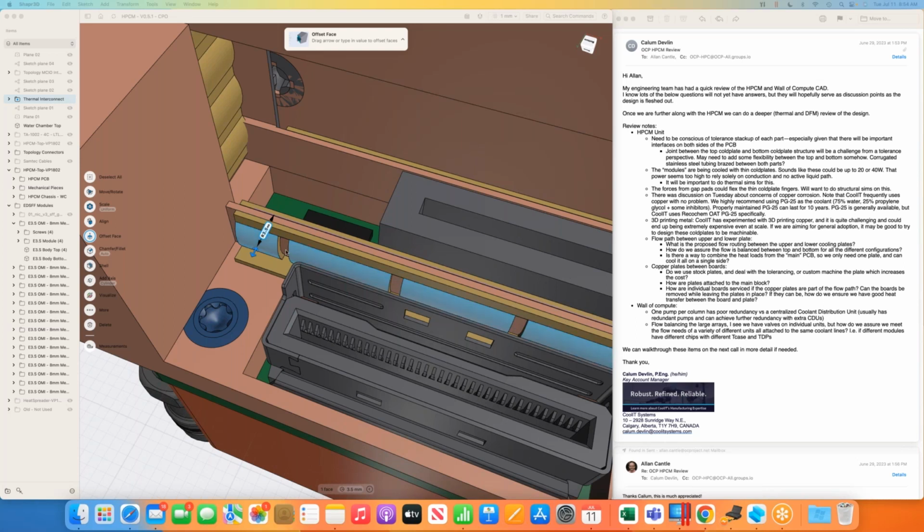In fact, this design is like this to make it look like the EMC shields we've seen. Why are the EMCs not one big solid plate? I'm assuming for some compression regions. But very good point. Yes, it has to do with insertion force, but remember, any gap becomes an antenna. Any straight edge, if you will, becomes an antenna, or this area becomes an aperture, and it can start to radiate electrically. But thermomechanically, you can have resonances.